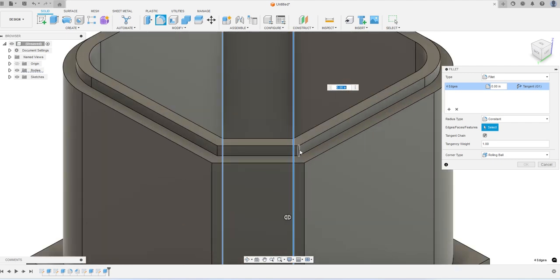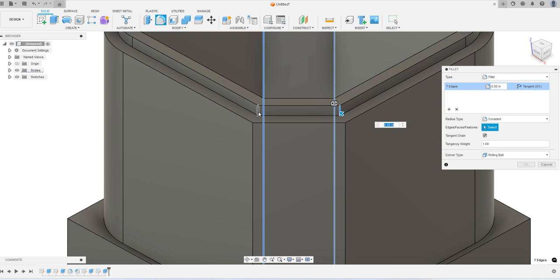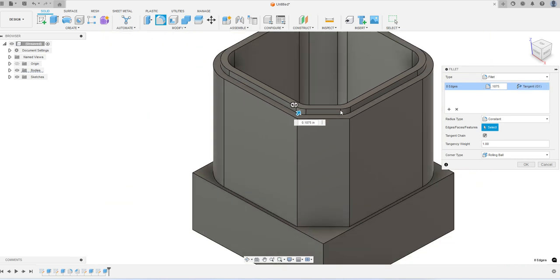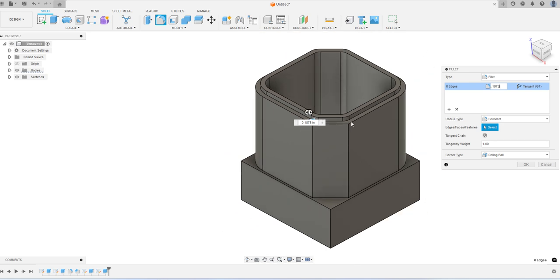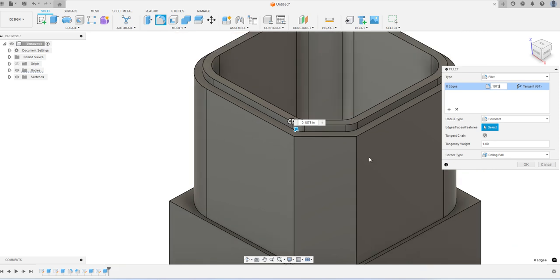Additionally, we have these short edges right here and here, and then the matching ones over here. They're on the outside and it will mill just fine right there, but those are going to be matched with the lid, and so those have to be round as well. The smallest we can work with is 0.1875, and so I made that 0.1875, and you'll notice that I rounded that area where an inner portion is going to meet with it, so it must also be rounded.